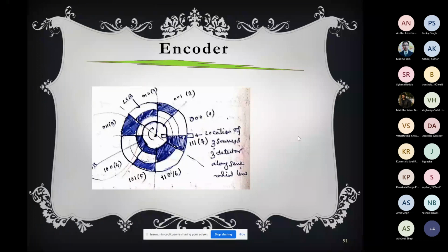In this case, whatever I said is very crude. One problem will be there, because you need to run this code, and after some interval the code will check the parallel port, and it is not dedicated. So you cannot check very frequently. The frequency of reading the parallel port should be quite low. Suppose you want a gigahertz range refreshing rate or sampling time. You can call it a sampling time because after that time you are reading it and restoring the data.